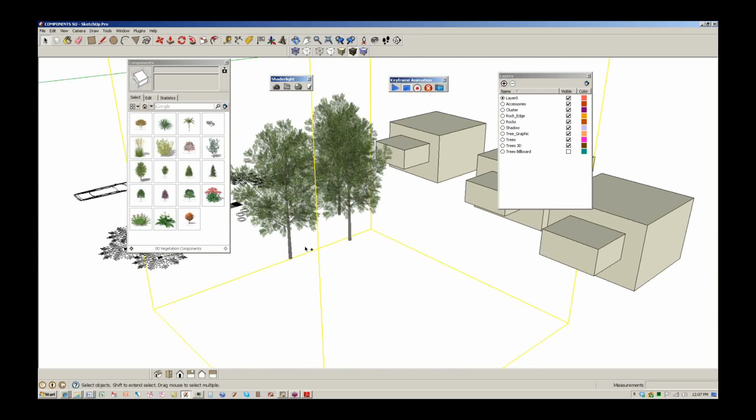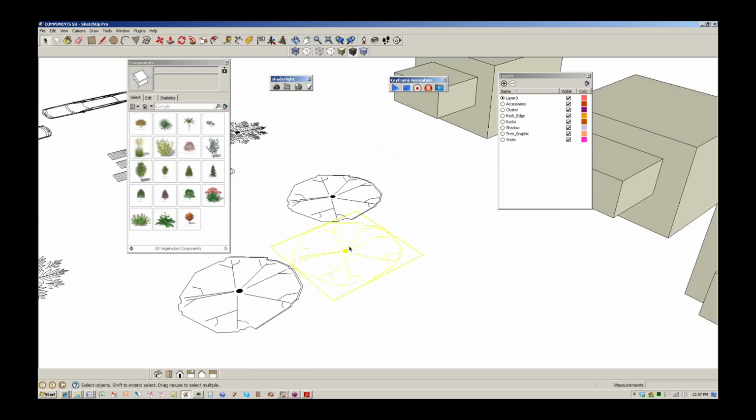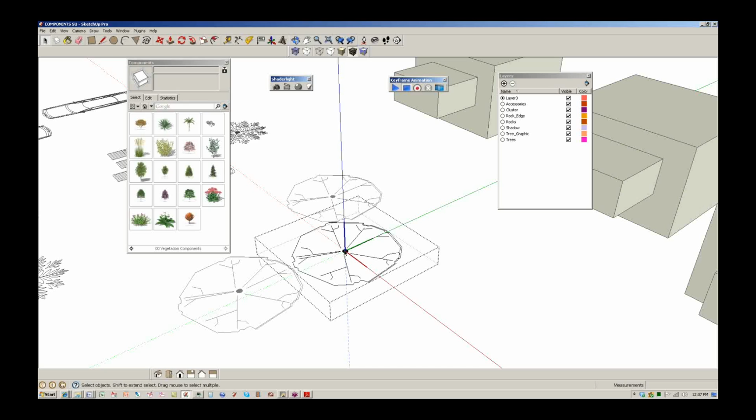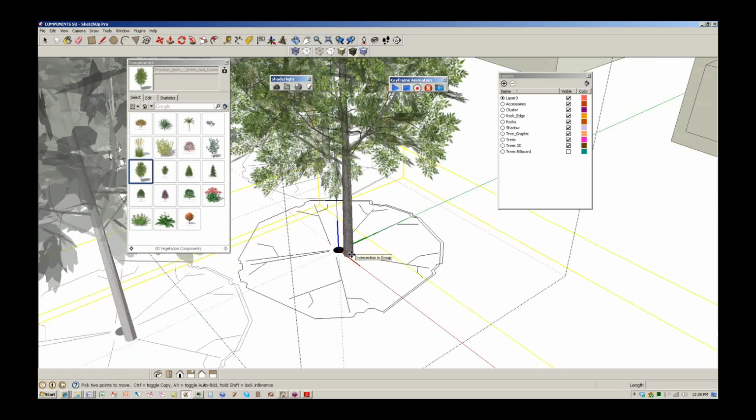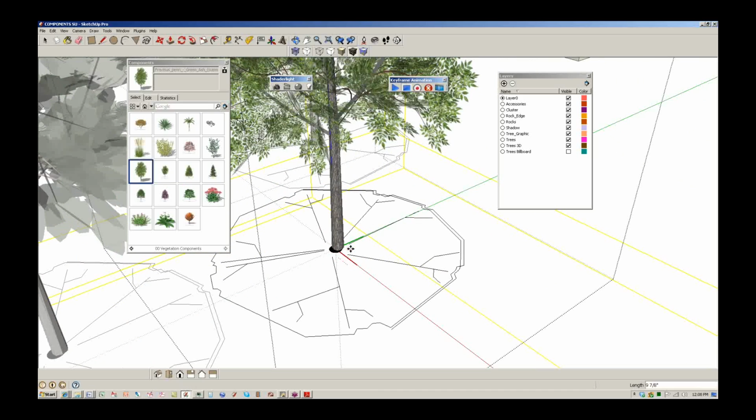Absolutely. I've noticed some problems with doing it that way. What happens when you do it that way, sometimes it's going to shift it away from the axes depending on how the component was created. If I go into the component instance and then drag it in here, I have a reference, right? I know exactly where this belongs.